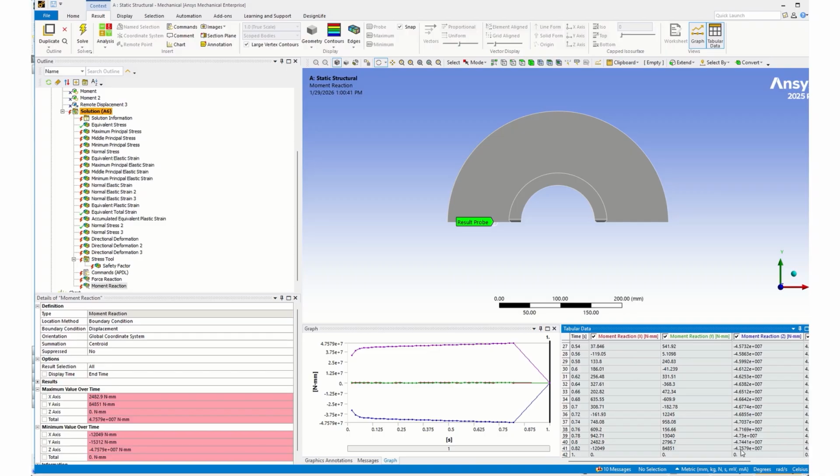And so that would be my fully plastic moment based on the moment being applied from the center of curvature in this beam. And that number was quite a bit different than placing the moment here. This moment might be more realistic in this model, but to match theory, the moment applied right on this face matches theory better, and that's why our answer before matched the theoretical results and the hand calculations better.